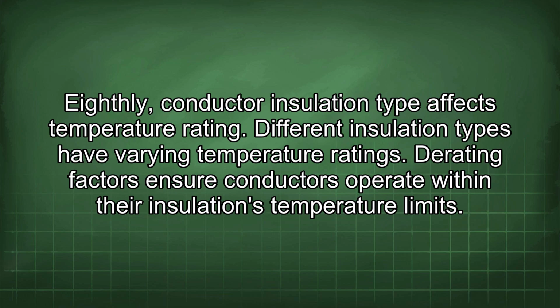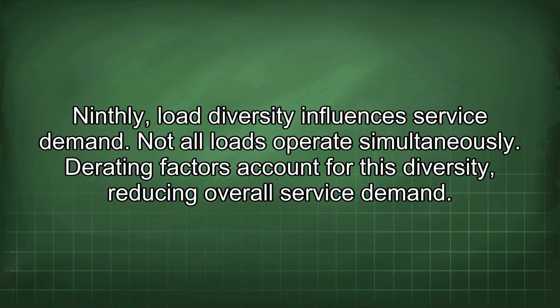Eighthly, conductor insulation type affects temperature rating. Different insulation types have varying temperature ratings. Derating factors ensure conductors operate within their insulation's temperature limits. Ninthly, load diversity influences service demand. Not all loads operate simultaneously. Derating factors account for this diversity, reducing overall service demand.